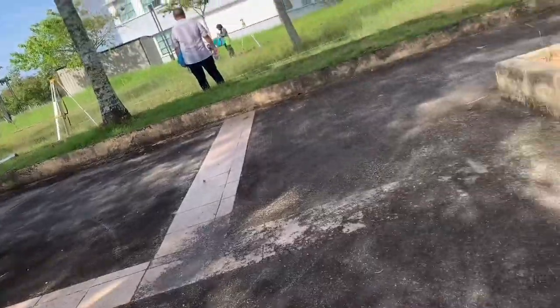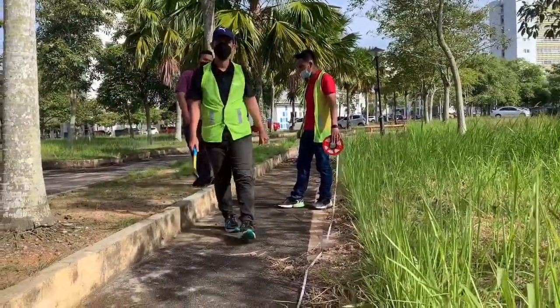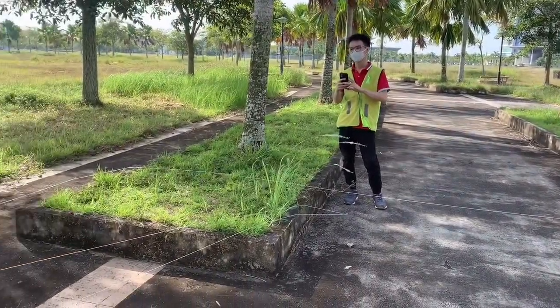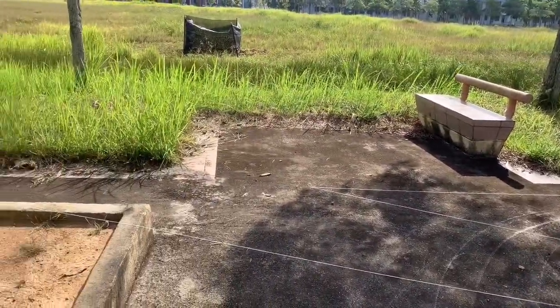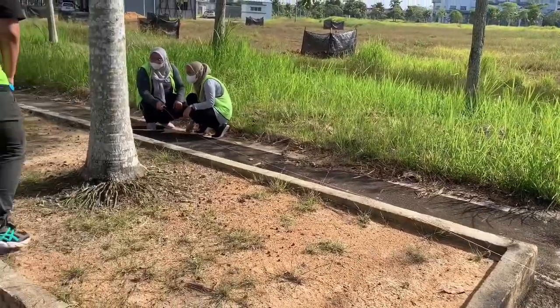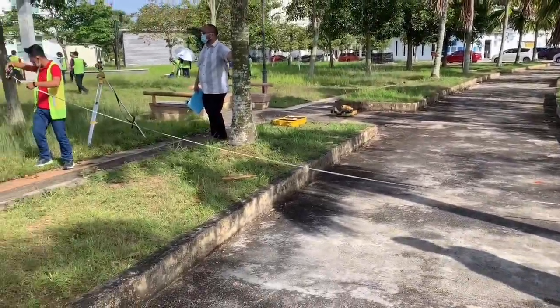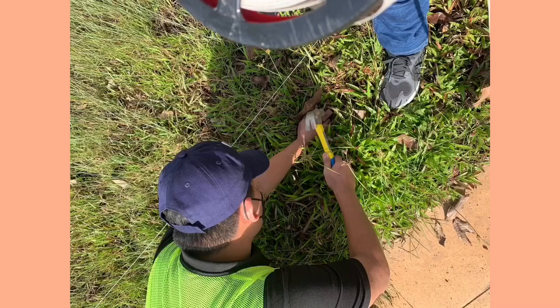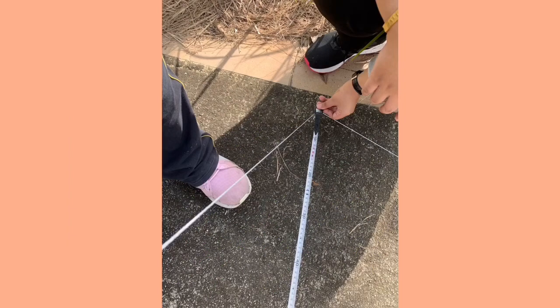Then mark the two corners of the building, points A and B. They are marked on the road, the first using wood spikes measuring 50mm by 50mm by 300mm. The exact row of the corners of this building is marked on the spikes at points A and B. Above the road line AB, plant a spike at F at a distance of 3 meters from A and nail in this spike exactly 3 meters from A.